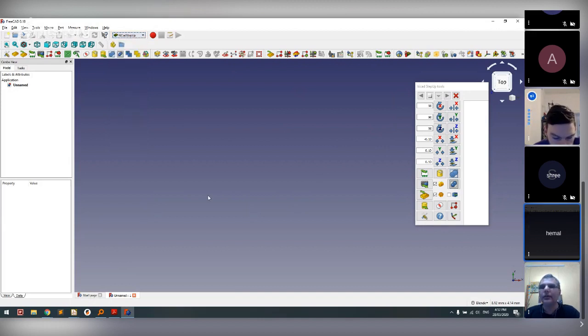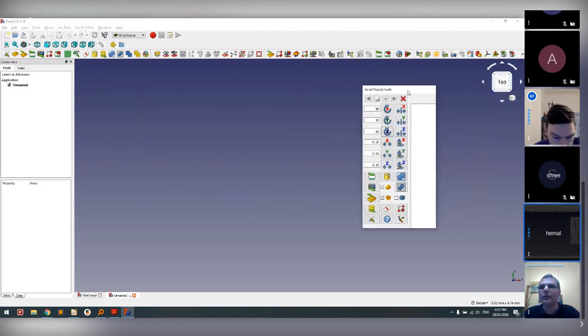I have it open, but the toolbar doesn't pop up. That happens. You can probably go to View, Toolbars and enable it. If you import a footprint or a step file, the floating toolbar should pop up.